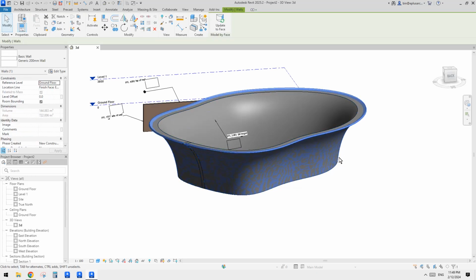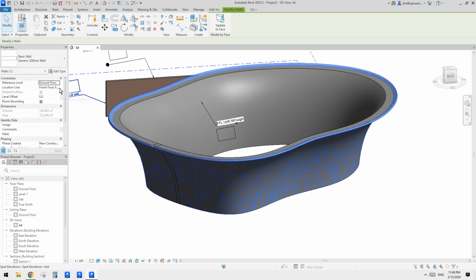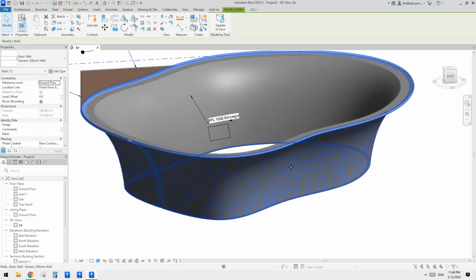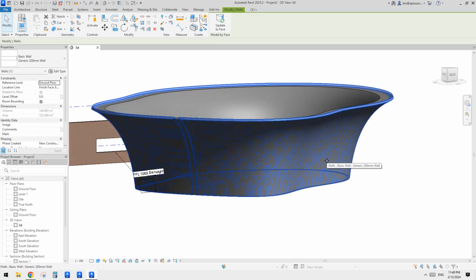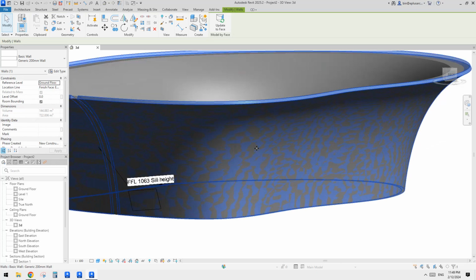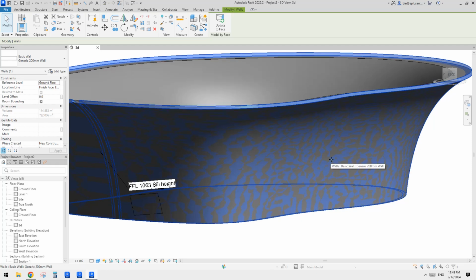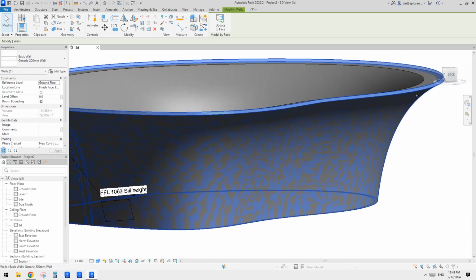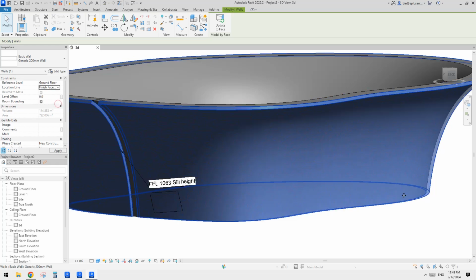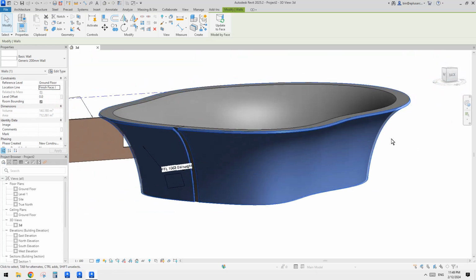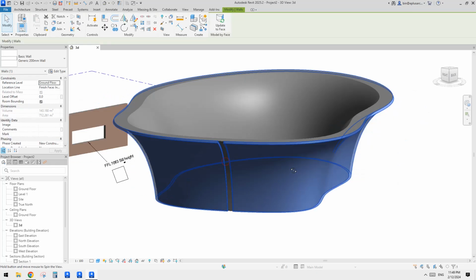So now see, this is the wall, and also you can choose which side of the mass you want to align with. So currently the wall is being placed, so you can see all this color. This means the surface of this wall overlaps with the surface of that mass. So you can change this from interior to, currently exterior to interior. It means the wall will be placed on the outside of the mass. Okay, so these are the options.